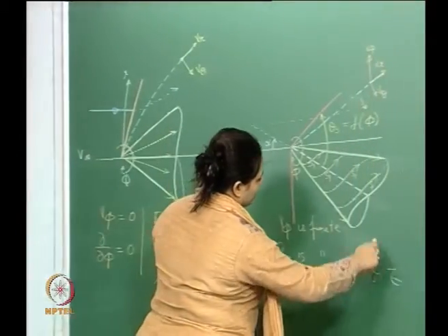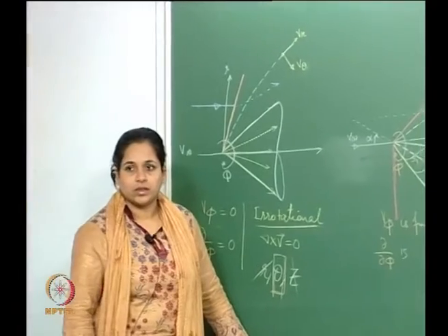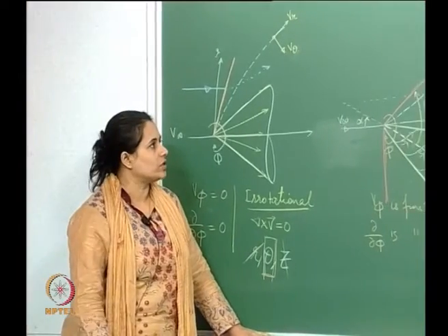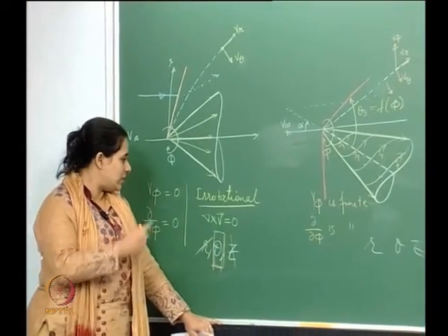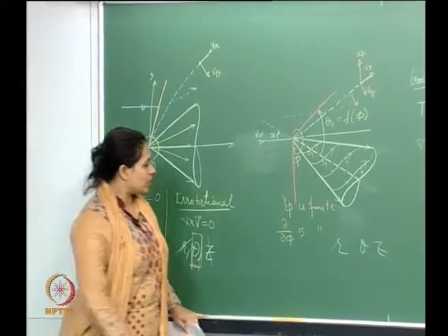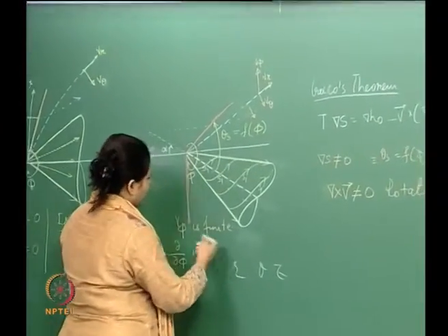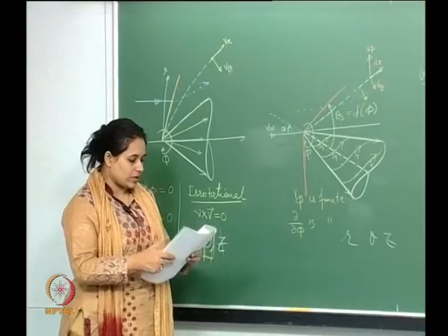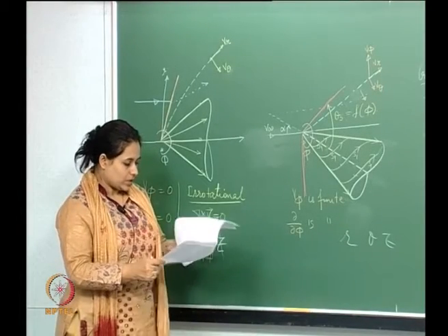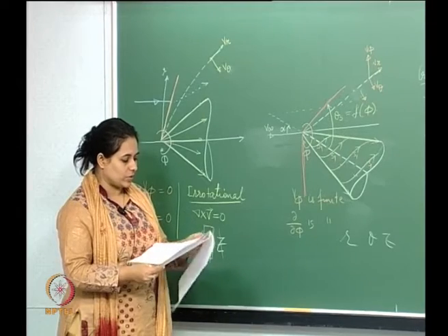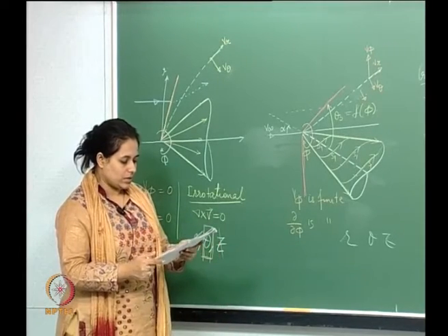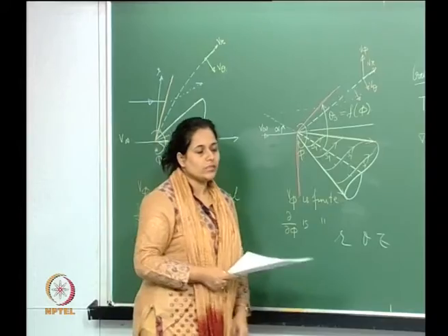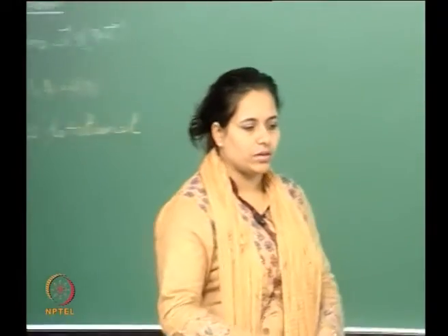Here, of course, we have two dependent variables, theta and phi, unlike in the previous case. So, here of course, again del phi is finite, V phi is finite. Okay. So, having come to that, for conical flows we use the Taylor-Maccoll equation, and we solved for it.